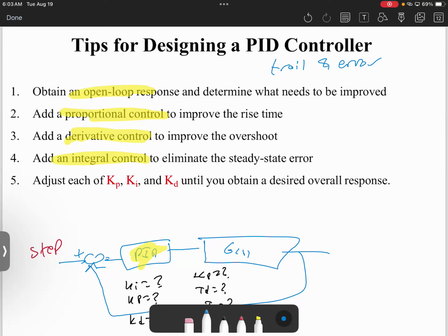Try putting numbers. Try like open loop. Then let's put P as 10. Then let's put D as 1. Then try a step. Run the system. Then add the PID controller, run the system, monitor this. If, for example, it's very high or unstable, change P, reduce it to make it stable. Then add the D controller, add I. This is one of the trial and error ways, and it can work. It can be okay, but it's not recommended.